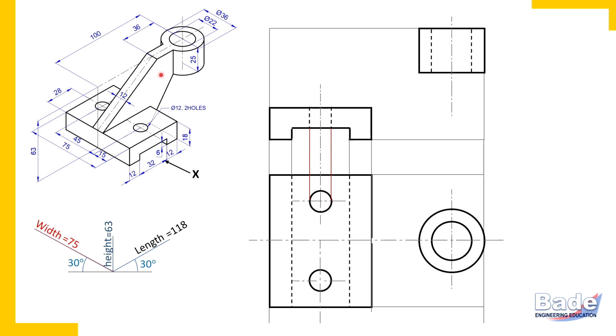So how to draw plates? Largest surface, that is shape in a view, remaining two views are thin strips. So let's continue with this plate. 36 millimeters. From center, parallel to length. Length appears in the front view. So from center, that is axis of the cylinder, 36 millimeters, parallel to length I have measured. So this is how we have located this corner in the front view. Okay.